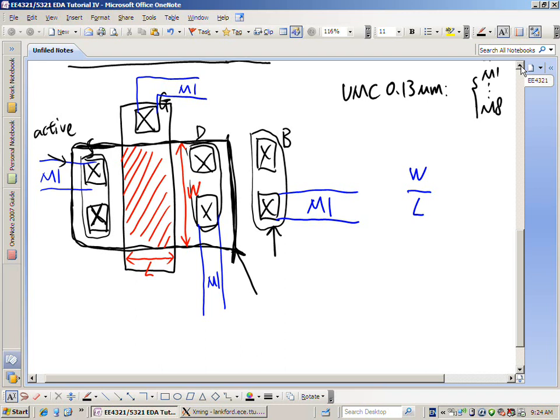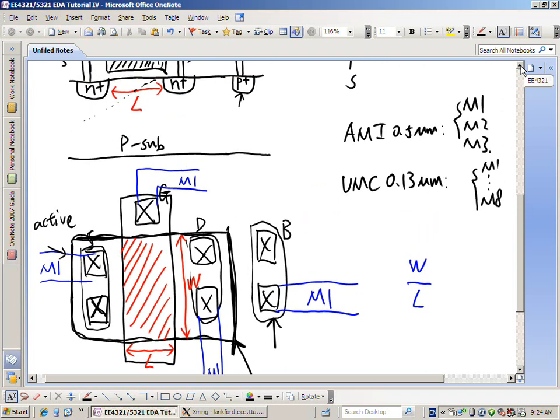Okay. And when we make a contact to the N-well, does it know that it has to add additional doping at those points to make an ohmic contact? The question is, how do we tell the company that we want to make additional doping? Actually, when you draw this active region, it's telling the software where the company has to do additional doping for the transistor. They will identify where the contact is, and they will implant the N+. It's totally automatic. You don't have to do anything. You just need to draw this figure. Okay? Any other question?